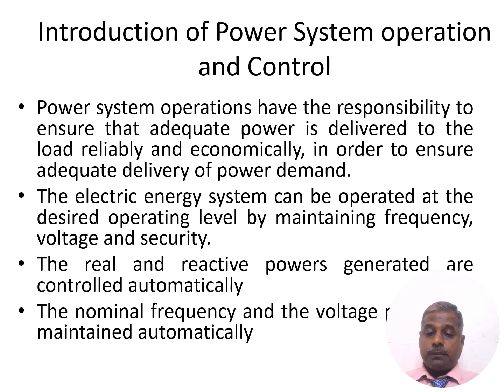Whenever you are supplying voltage and frequency to the customers, they should be at nominal values. Variation of the voltage and of the frequency is not allowed. Even if a variation is present, it should be within a tolerance or acceptable value. Beyond that value, we can't allow the variation of the voltage.